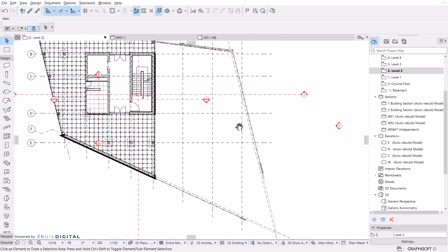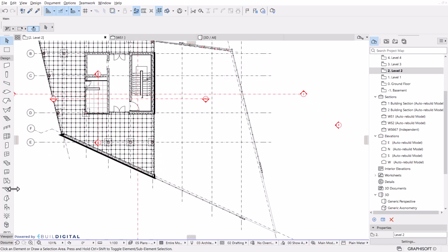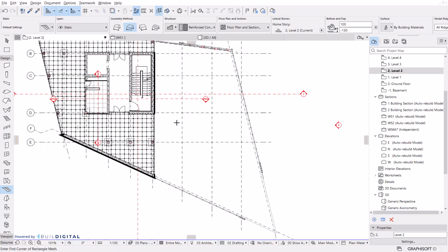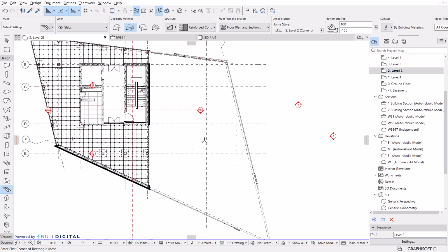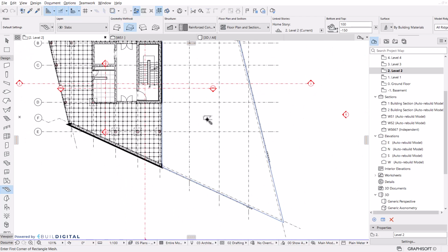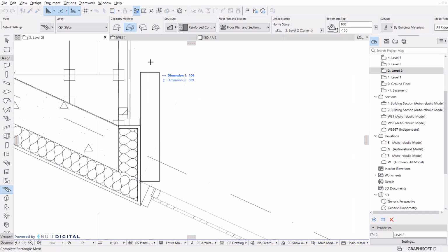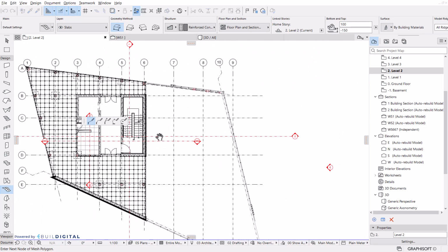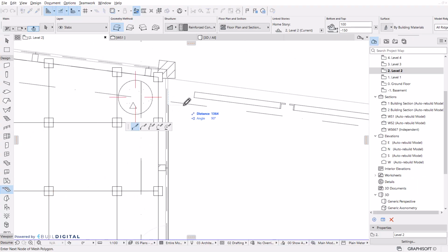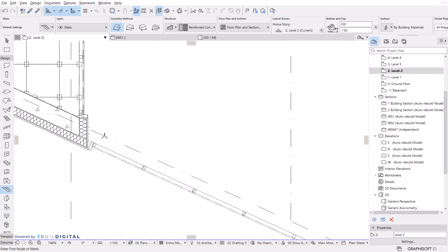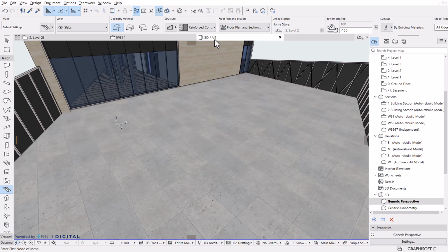And now let's focus on this area here outside and select the mesh tool. Then click on the favorites and use the concrete slab with top slopes. Just double click on that. And now I'm just going to draw manually, or you can try using the magic wand, the edges of this roof area. Like so.